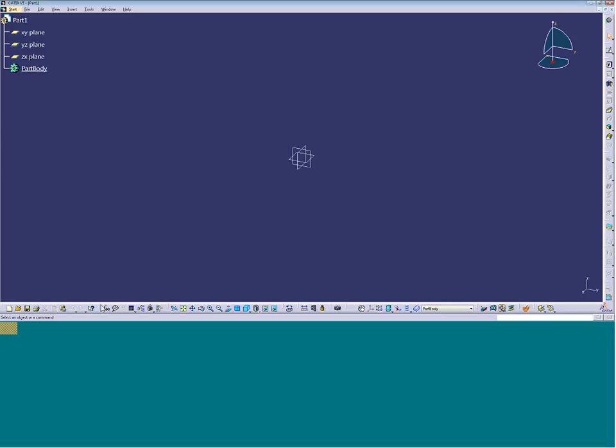Development was done almost entirely in VBA, and really a lot of that is using these tools that we see here, the common knowledge tools that are available in any workbench of CATIA, along with a subset of the Knowledge Advisor workbench. But really, these tools here are your fundamental tools in getting into KnowledgeWare and KBE in CATIA. I imagine that many of you by now, especially the experienced users, have built formulas and design tables and equivalent dimensions and so on, so I won't belabor these or how those are built. I'm going to show how they're deployed in a slightly different fashion than manual interaction.